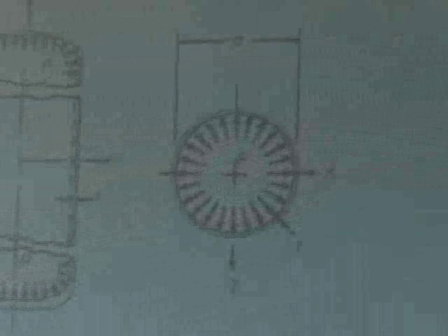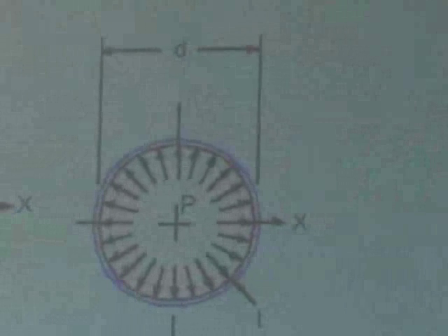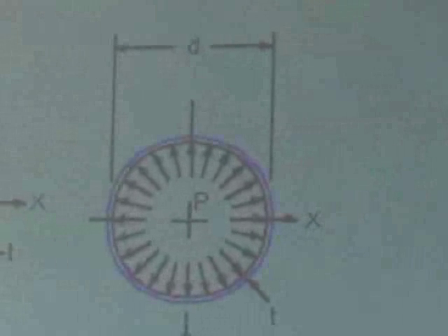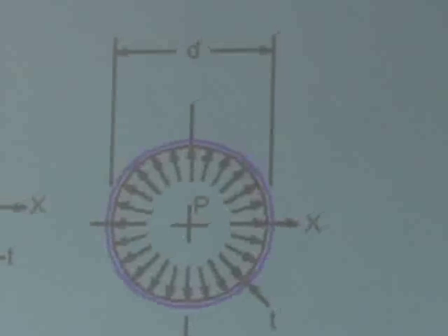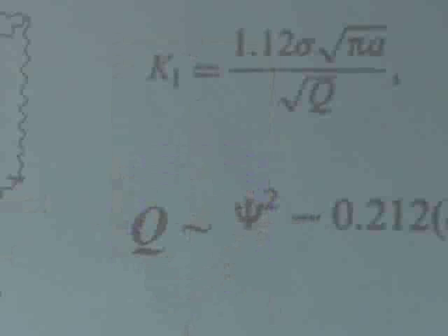The hoop stress is about twice as high, so that tells us from the geometry that I've put on the board that we'll be more worried about that seam weld that I've put on. So if it's a thick piece of steel, we'd be looking at making a high quality groove weld that we talked about. If the vessel is big enough, we'll try to weld from both sides to avoid having a root that has defects in it, or imperfections anyway. So it's kind of the approach to think about when you really go out and say, oh, I'm going to build this.